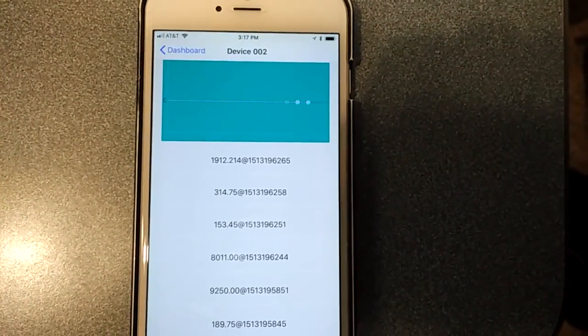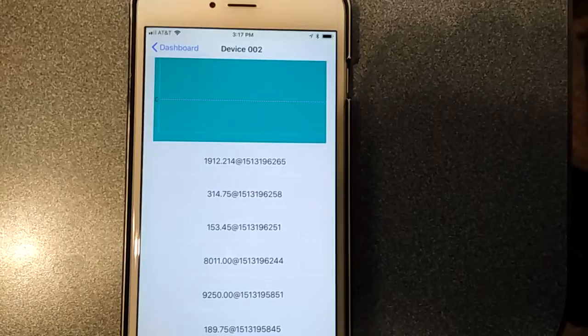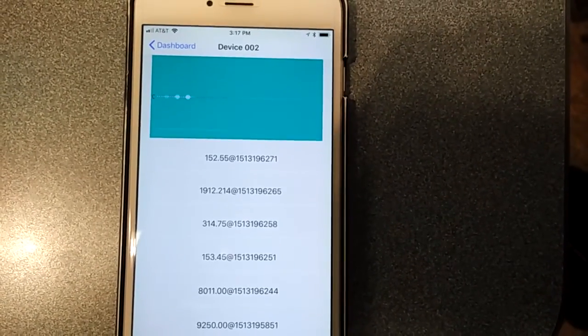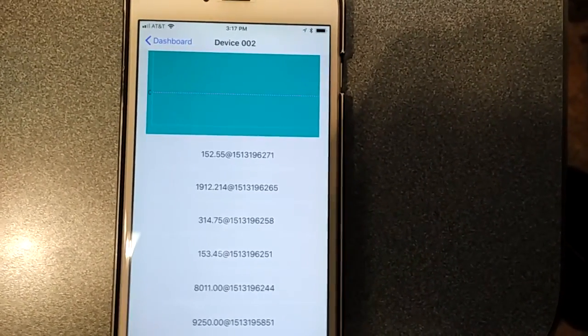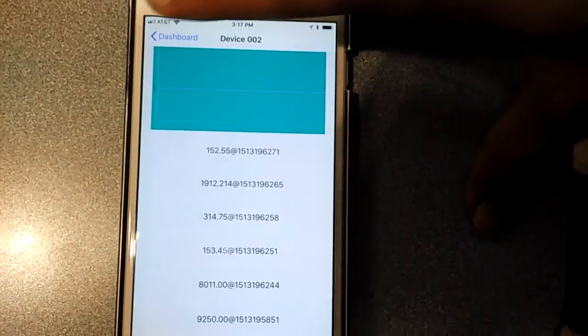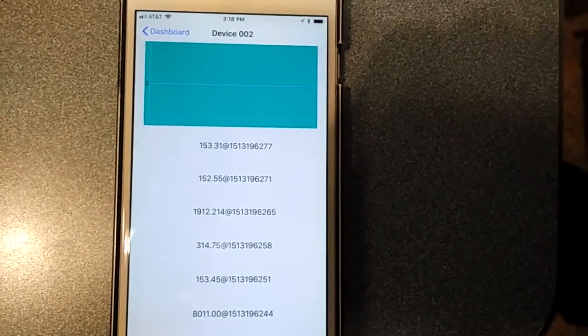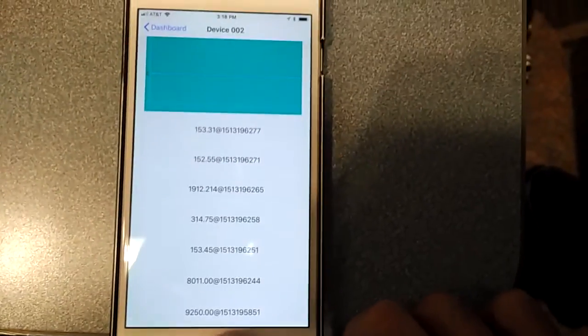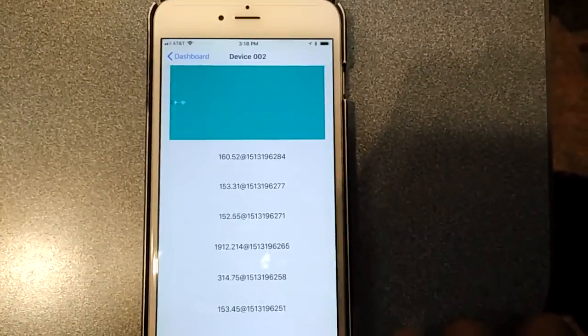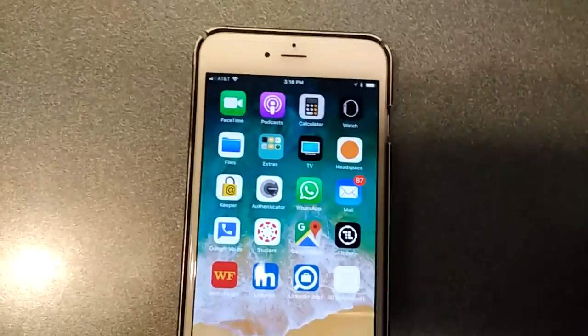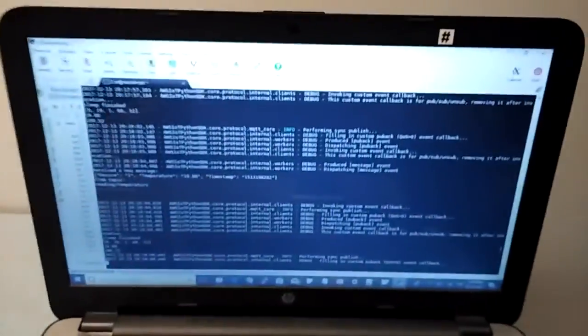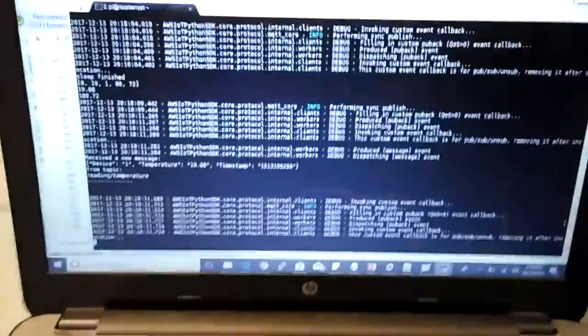And the microphone sends up the frequency after the FFT. So this reading we're getting is in the form of frequency. It's right now settled at 152. The fluctuations are quite high because we're in a very quiet environment and it's sensing my voice. But we tried and tested this using a tuning fork with 500 hertz of frequency, which we could successfully sense.